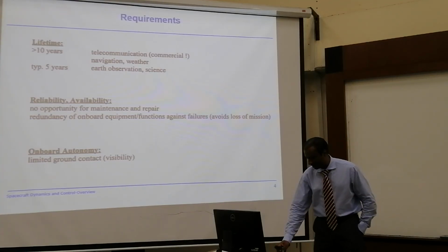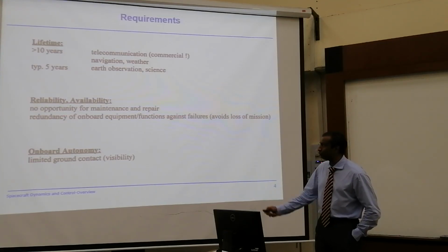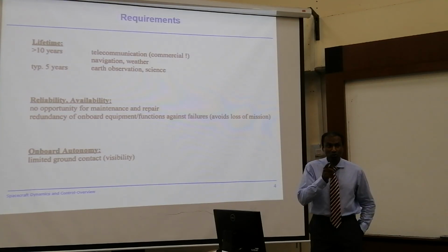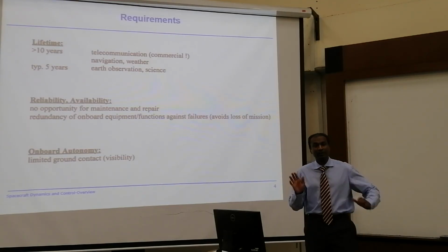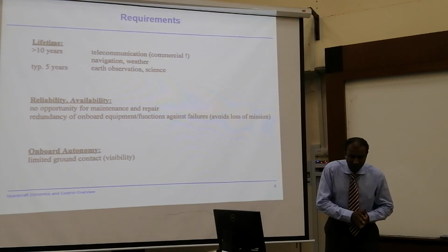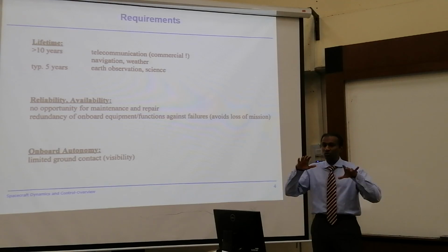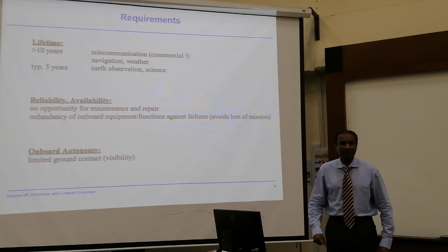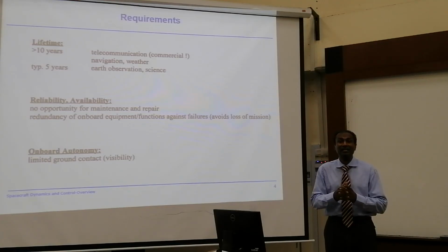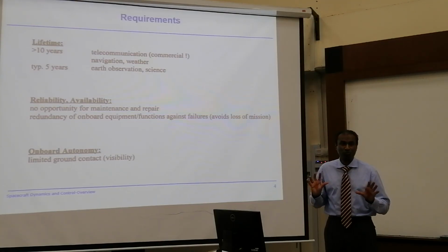In satellite technology, as we mentioned before, this is very prone to failure. So for an active control system, our redundancy policy is especially important. Now, there are two redundancies that you can do. You can do software redundancy, you can do hardware redundancy. If you try to do hardware redundancy, you'd better fly two satellites separately. That's what happens, let's say, in GPS. GPS has a lot of satellites, right? Clusters of satellites. They also have backup satellites together.